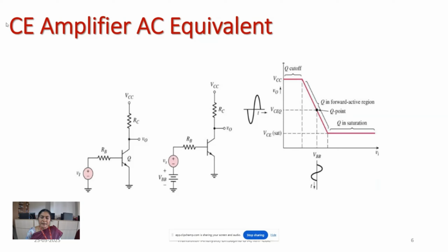Now for the output, you can see the relation between Vi and VCC, that is the input and output voltage relations. There will be a quiescent operating point, that is a point at which the transistor works properly, and that happens only in the active region. And when the input is changed, we have the cutoff region, which is below some value of your IB or VB, and similarly the saturation region when it exceeds the biasing, when both junctions are in reverse bias conditions.